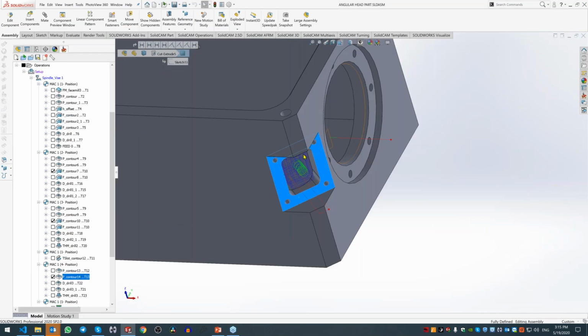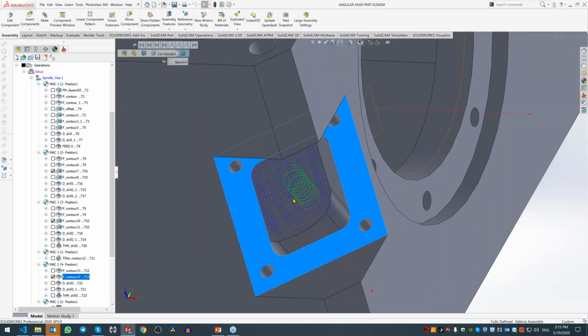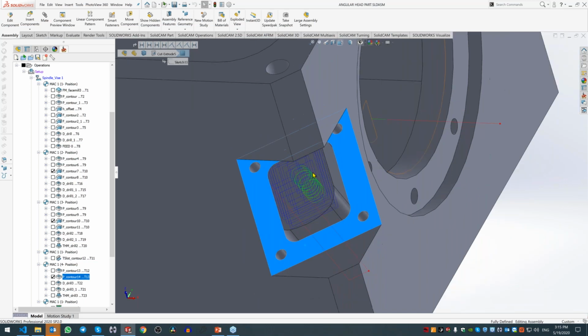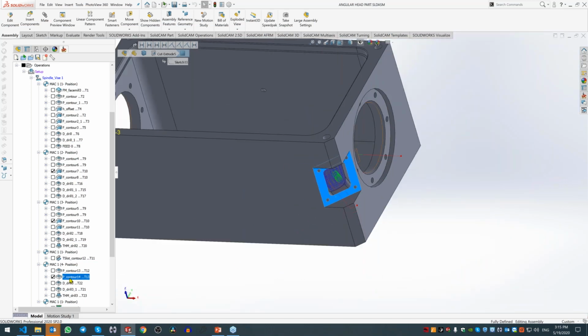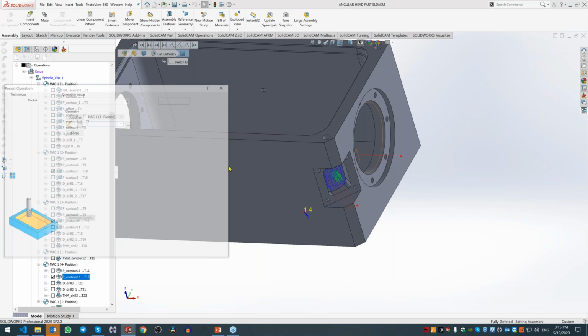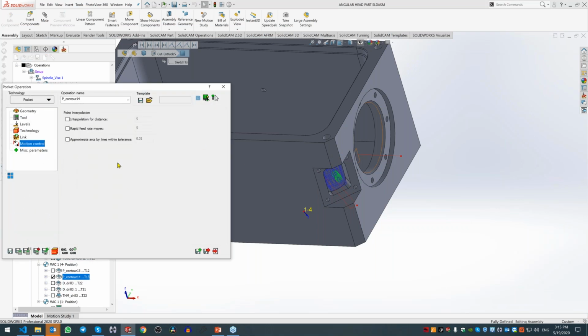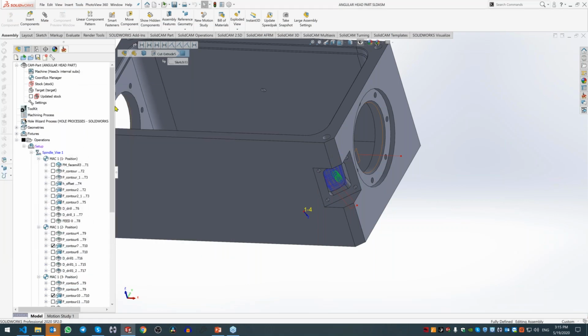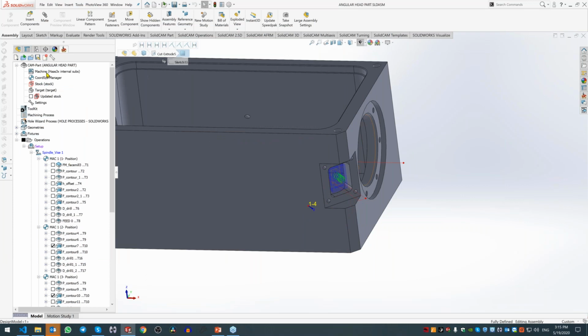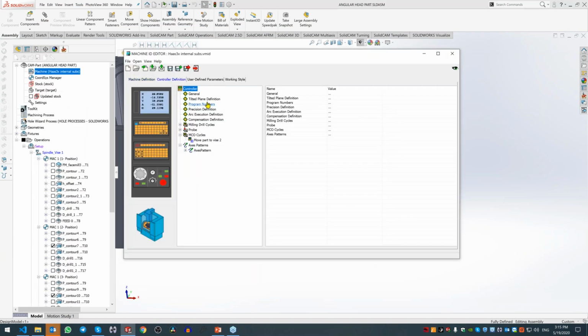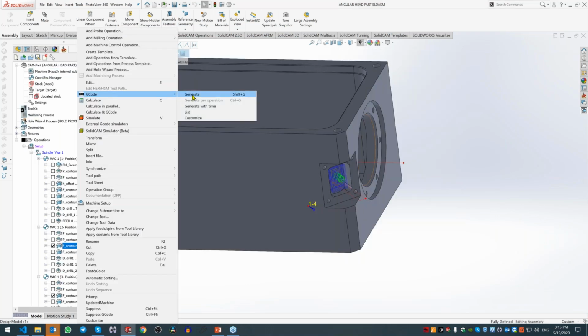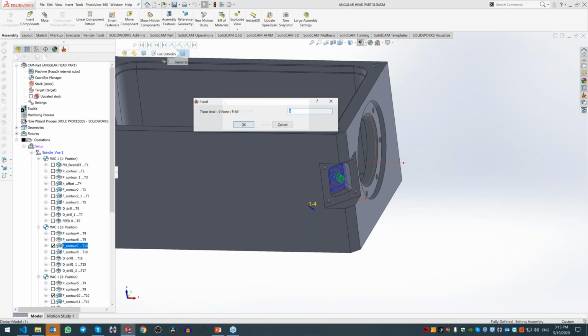So this operation will automatically split arcs to lines because it's not in the plane. In the post-processor, you don't need to define anything. And of course here, you don't need to split it manually. Okay. In the second case, if I define a plane in the machine like a custom one, and I will make a G code for it. So I will make it with trace 5.